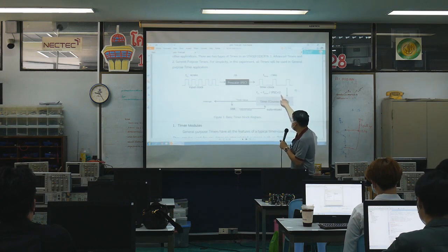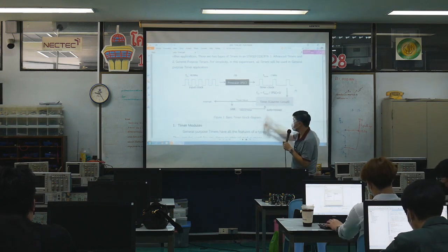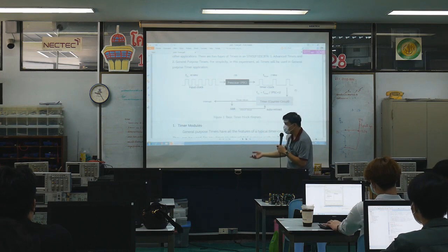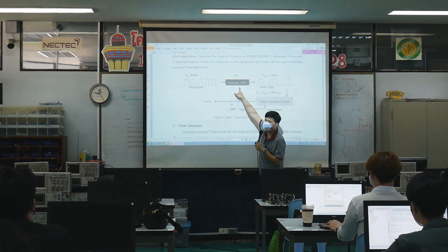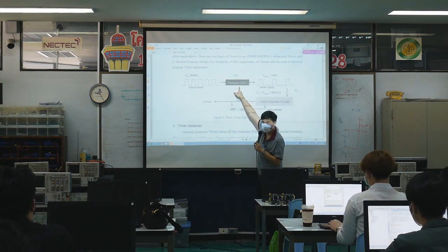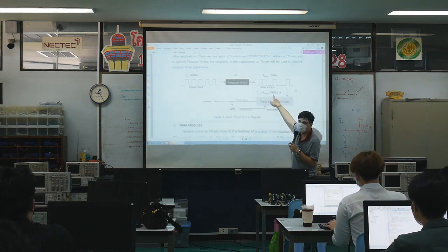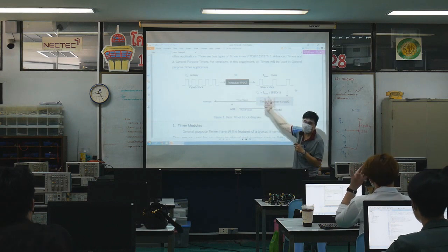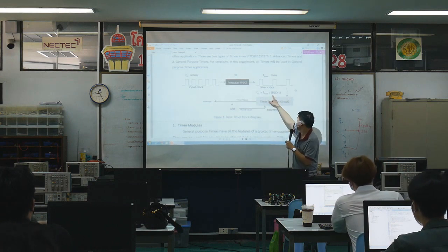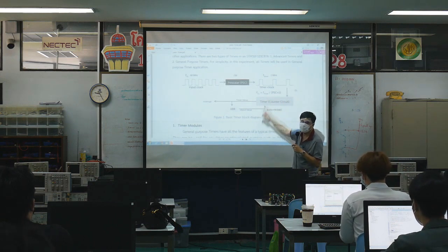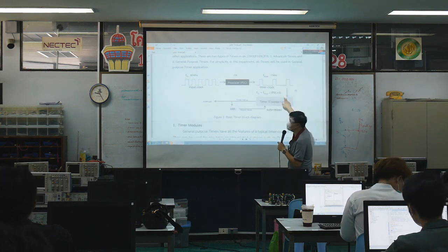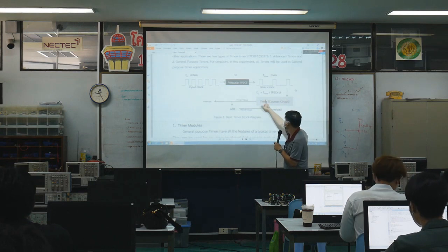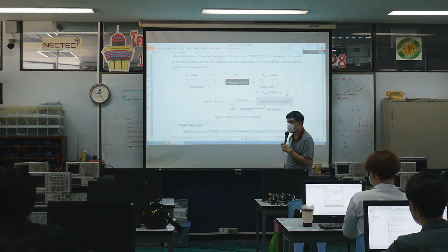Okay, why do we have to have a plus 1 here? It's because sometimes if you just ignore the prescaler, the value can be zero, and if you divide something by 0, you're gonna get a hard error. So that's why they add 1, to make sure that you did everything correctly here. Then the timer clock, in this case 2 MHz, goes to the timer or counter circuit inside your CPU.